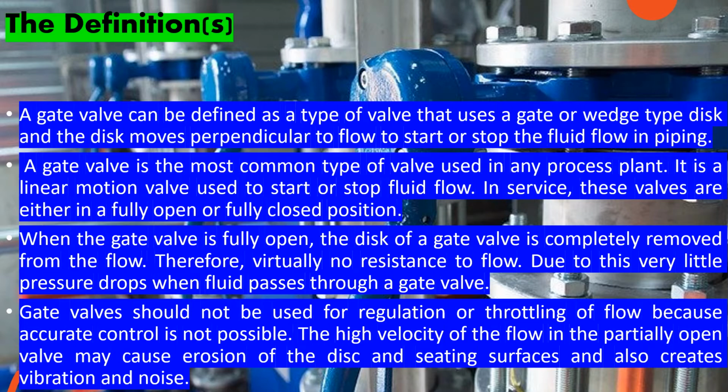When we talk about a fully open gate valve, the disc of the gate is completely removed from the flow. Therefore, no resistance is offered to the flow, and due to this, very little pressure drop occurs when fluid passes through a gate valve.